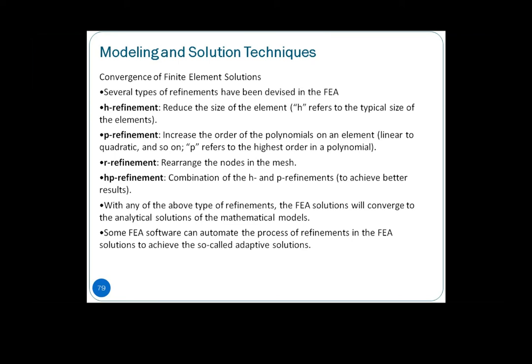You reduce the size until the change between two subsequent tests achieves the tolerance that you set. Then that is considered a good mesh result, giving considerably good accuracy and, at the same time, a good computation time.